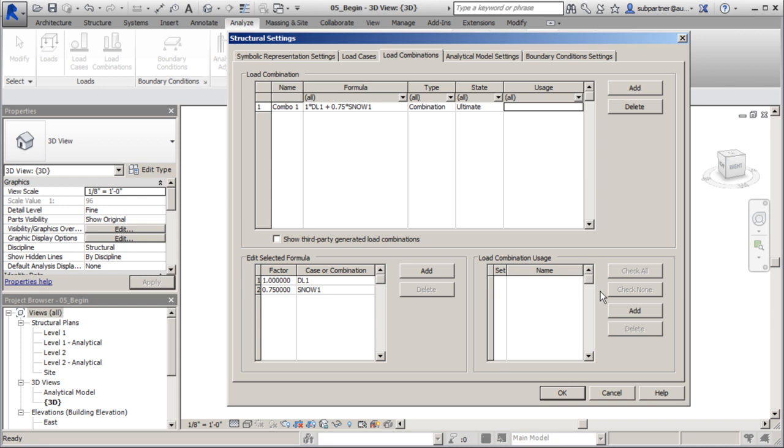That's where we'll actually need to maybe apply usage here. So we can maybe give it a name here. For instance, we could maybe use 2 loading combination usages here. Maybe something going in the Z direction, or maybe call it gravity, going up and down. So I'm going to type in, give this guy a name. We can add another one, and maybe we'll want to have a usage for a situation with things going laterally, so we can say lateral. So now I can click on either one of these and it'll appear up here. So now we've created our own usage category.